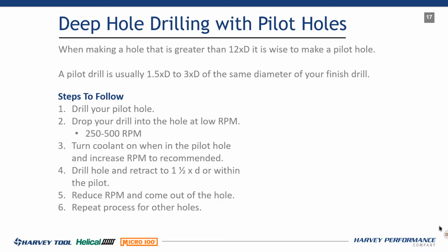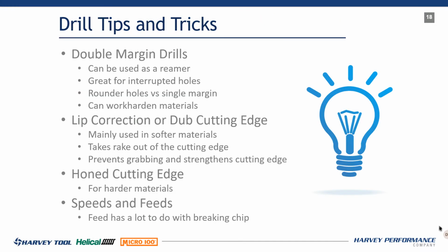Very important, because what you get is a drill that's spinning around at high RPMs depending on your material. There's a lot of centrifugal force going on, and that drill wants to whip. So it's very important to do that actually with a pilot drill.